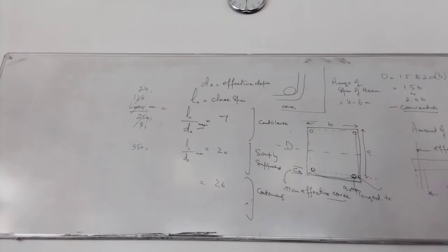So you have 24 mm as the final deflection that you are getting here, in that case, for example, when it was a 6 meter beam. Now you know from structural analysis how you measure deflection. But the deflection of the beam that you get from structural analysis has to be less than 24 mm for this beam if it was 6 meter without partition in between. So this is the limit.